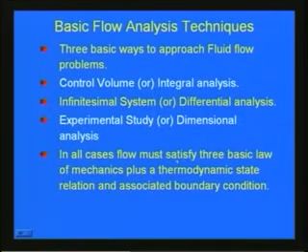In all these cases, we have to see that the flow satisfies three basic laws of mechanics, the thermodynamic state relationship and the associated boundary conditions. The three basic laws of mechanics are the equations or theories derived based upon the conservation of mass, conservation of momentum, and conservation of energy.